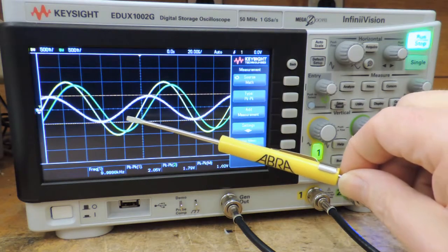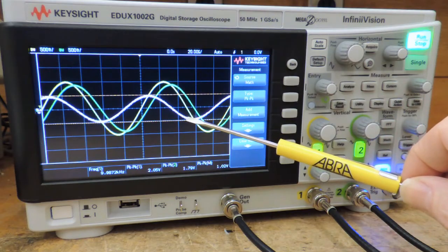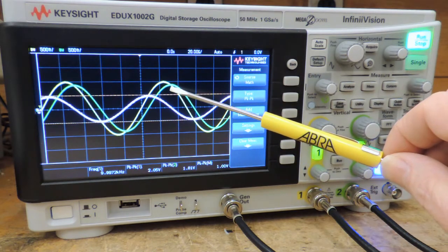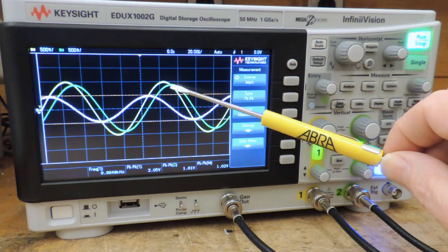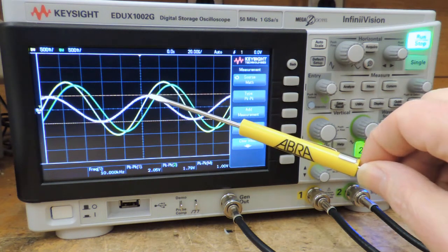It's also the phase angle for the current going through our circuit, because voltage and current going through a resistor share the same phase angle. So the voltage drop across the capacitor should be 90 degrees out of phase with the voltage drop across the resistor. So that looks like it's correct.